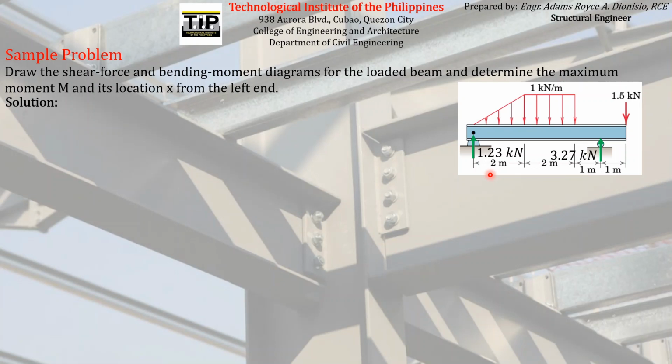The second step is we have to establish the critical points on the beam. So what are the critical points? Obviously, these are points, but how can we say that a particular point is a critical one? So usually, we take these things that I will enumerate as critical points. First is the location of support. So the locations of support, we can denote those as a critical point.